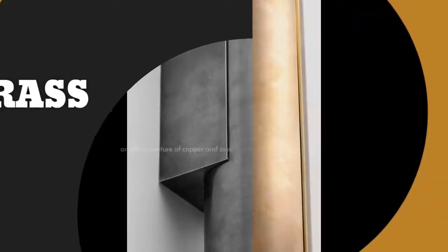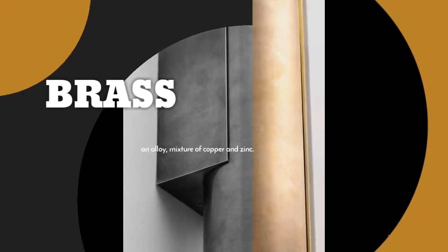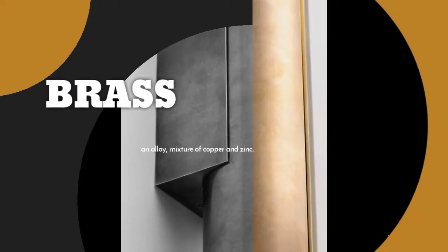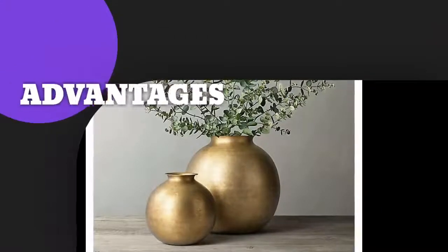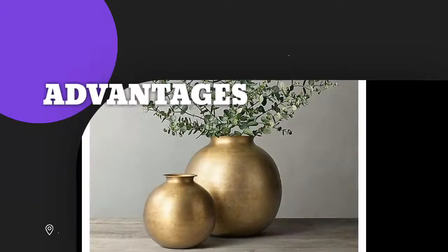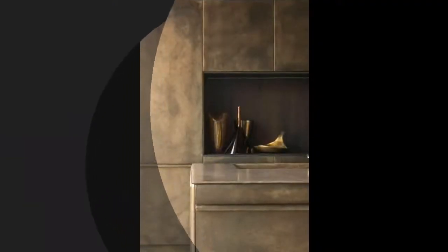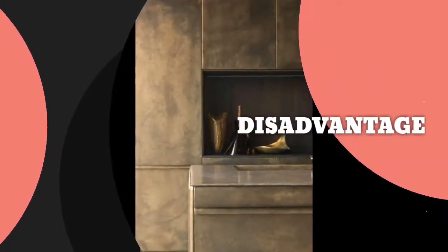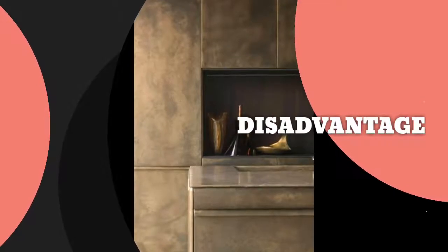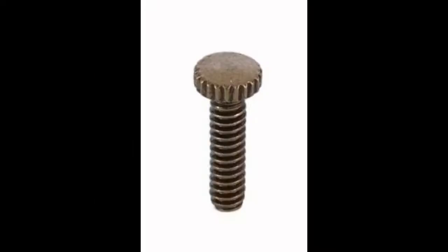So first up is brass. Brass is an alloy or mixture of copper and zinc with small quantities of other elements added onto it to improve it. In terms of advantages, brass is superior in workability and resistance to corrosion, but its downside is that it's less hard and strong than steels. We commonly see or use brasses in lightweight things such as doorknobs, screws, nuts, railings, and more.